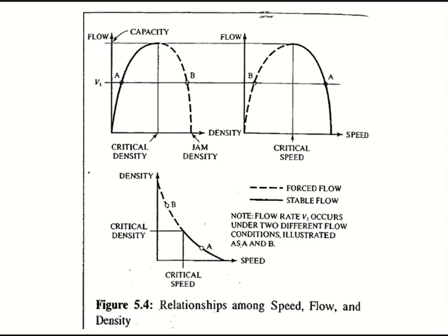So it starts from here when everybody was approaching and moving continuously until you reach the peak, which is the capacity. After capacity, more vehicles approach, they form a queue, and the queue reduces the flow, and the queue keeps on getting longer and longer, the flow keeps on getting lesser and lesser, until you reach this point where the queue has completely occupied the whole section. So the flow is almost now 0. Do you have a question? No? Okay.